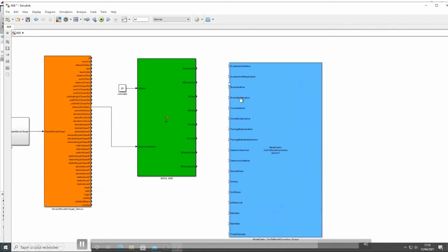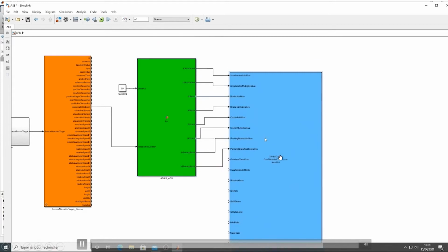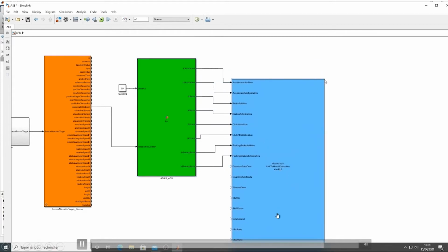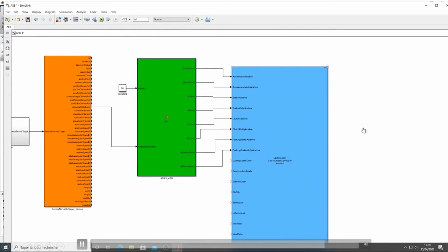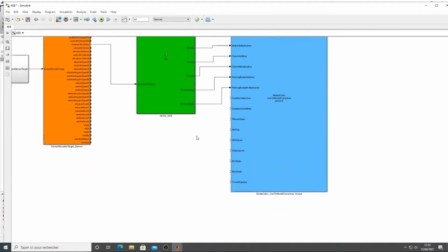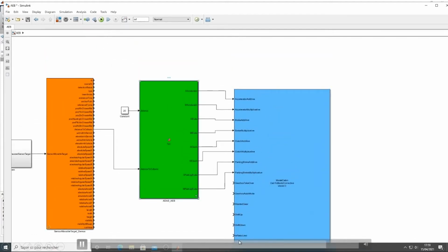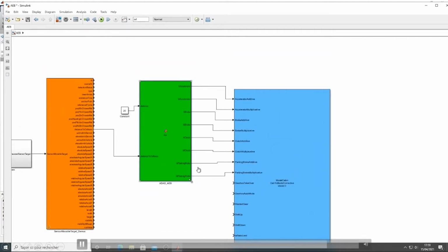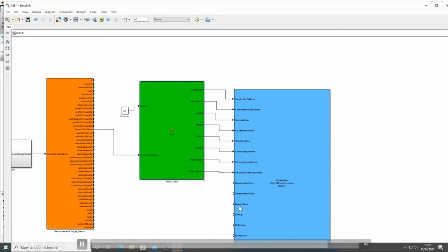And it takes as input accelerator value, brake value, clutch, etc. So we just have to link, and that will be fed into scanner. For the vehicle of ID 0, here it's a parameter of this block that we could change. And for the rest of the values that we don't have dynamic commands for, we can just use constants.